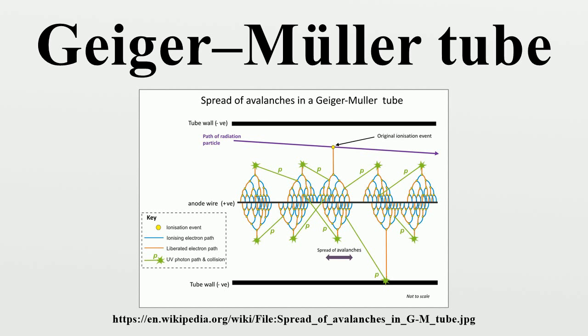Geiger plateau. The Geiger plateau is the voltage range in which the Geiger counter operates. If a GM tube is exposed to a steady radiation source and the applied voltage is increased from zero, it follows the plot of ion current shown in the lead section of this article. In the Geiger region, the gradient flattens. This is effectively the Geiger plateau. Depending on the characteristics of the specific tube, the exact voltage range of the plateau will vary.